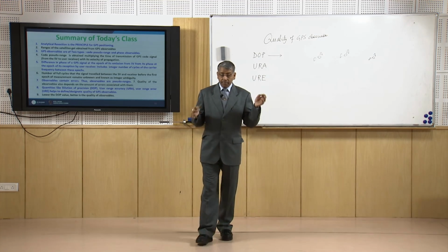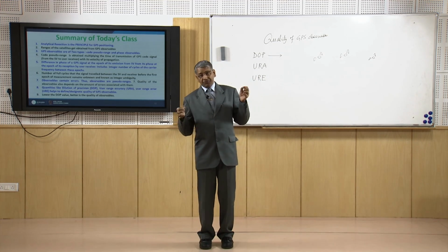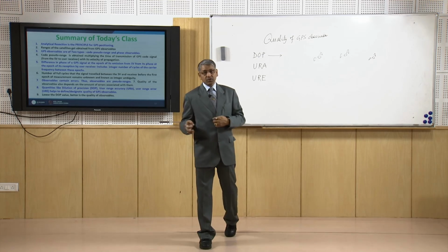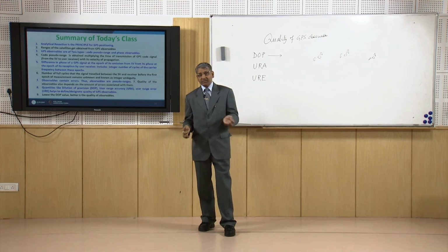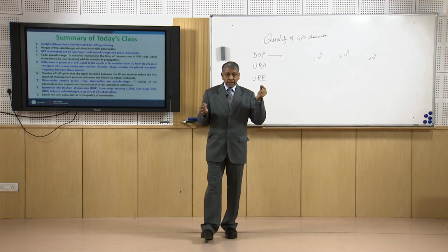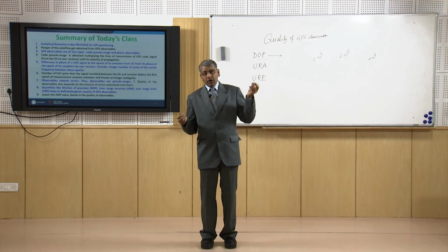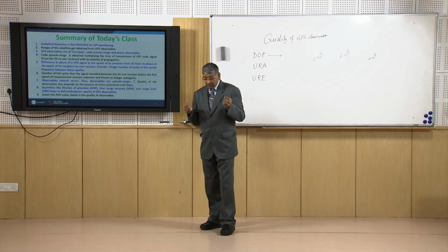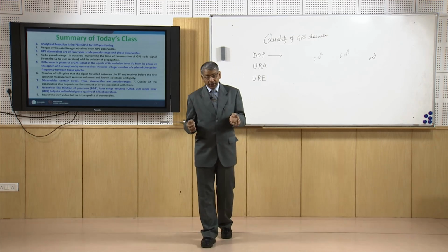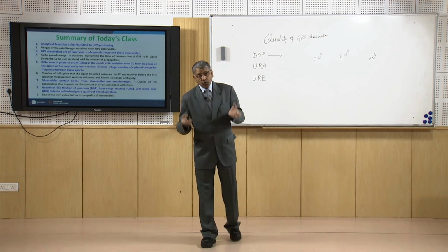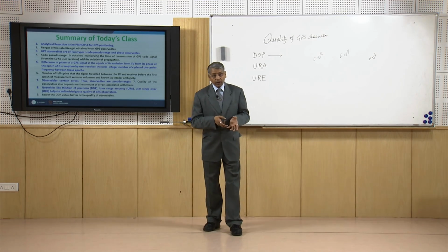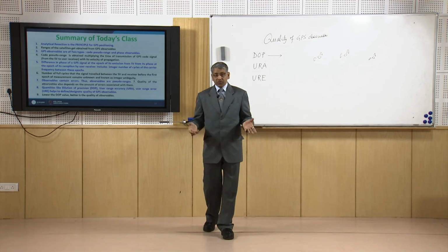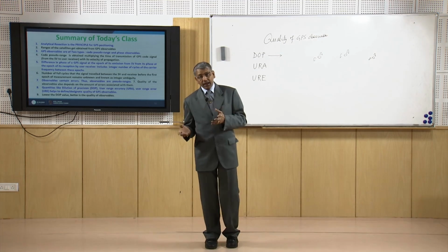But since there are different types of error associated with the signal propagation as well as the system, the range we get is not the actual range but a pseudo range, and that pseudo range can be computed in two ways: one from code, called code pseudo range, and the other from carrier.